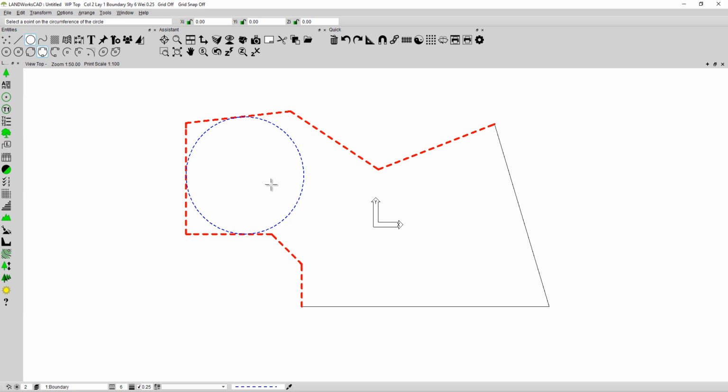In fact, for this particular exercise, it would be good to also check what happens if we were to do the same thing on a circle. So again, it's re-asking me, so it's repeating the last command. It's asking again to select a point on the circumference of the circle. So again, I'll pick another object, in this case this. Then I'll pick this one, and you'll see that it's tangent to those two objects. Notice too that as I drag it past the length of the purple line, it assumes the purple line is capable of being longer. And this would be true at this end as well.